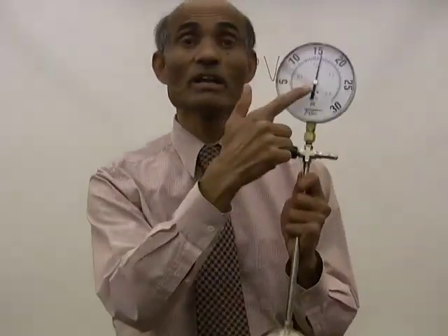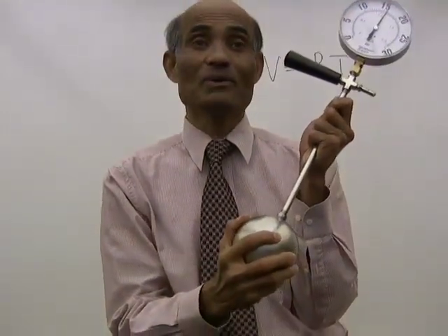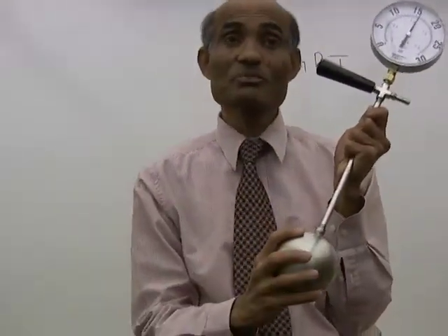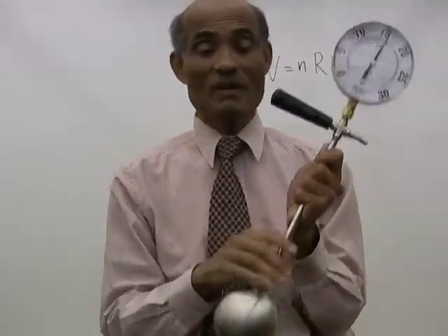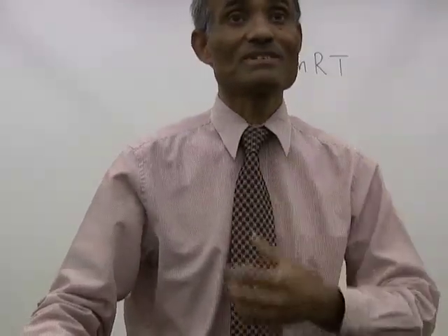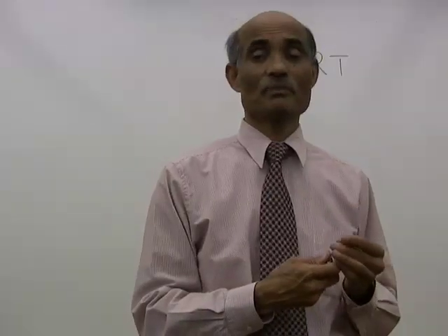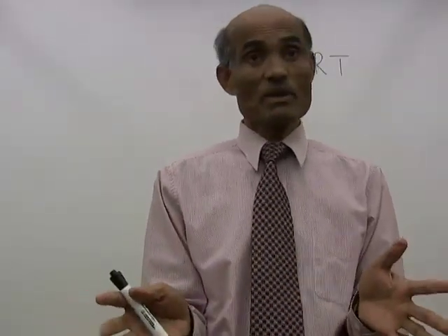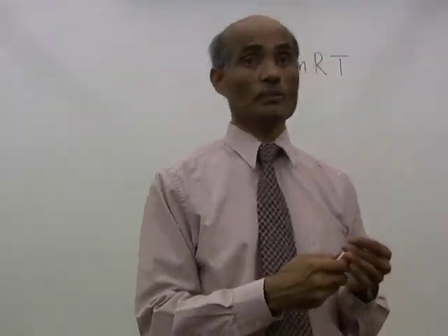Now we will also take the pressure readings while we allow the bulb to cool down, so that for each temperature you have 2 pressure values. Take the average. Now that will eliminate the errors that are present in this experiment. There are of course a lot of errors in all these experiments. Well, that will be the experiment. I will set it up and allow you to take the readings as we go on.